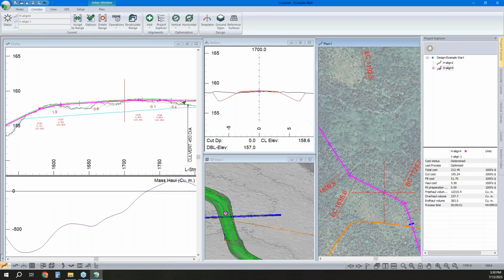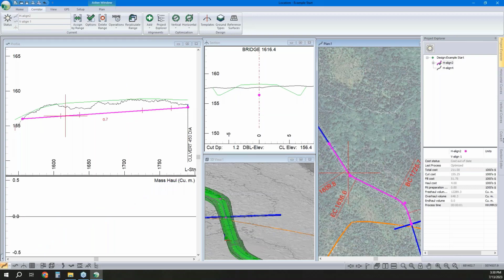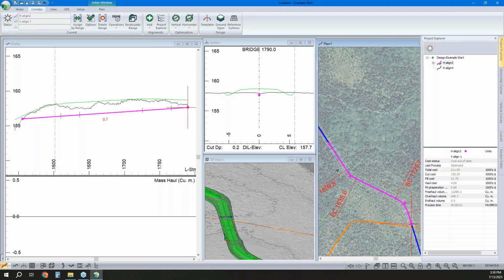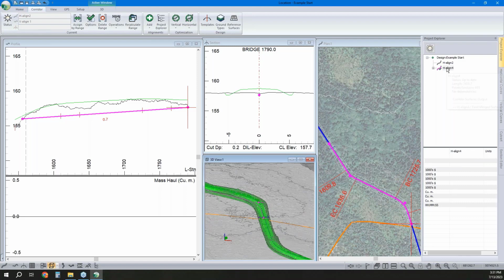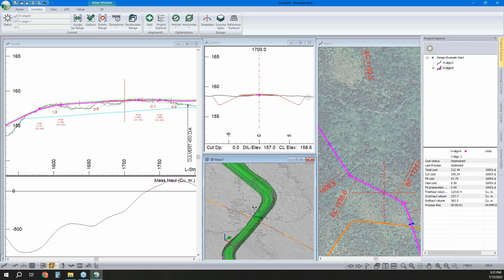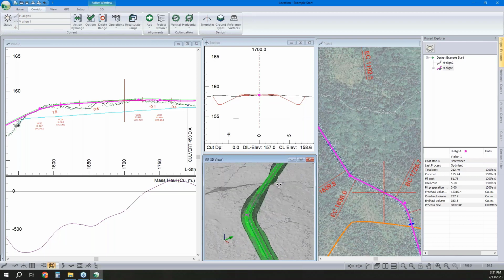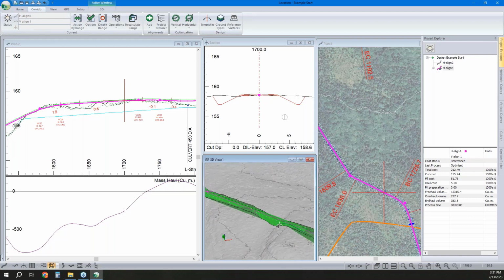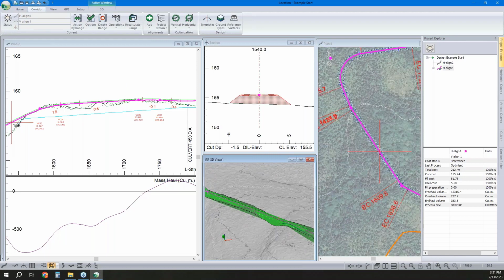And we can see that instead of having that ditch that follows our road grade, now the ditch is independent and away we go. Oh, and I just see something in my 3D that I don't like. Let's remove that. So there we are. That ditch goes deep and gets our water way back to here where, well, we've got a lot better relief to get that away from our prism. And here it turns out we still need a culvert, but at least we have relief to move that away once it goes through the culvert.